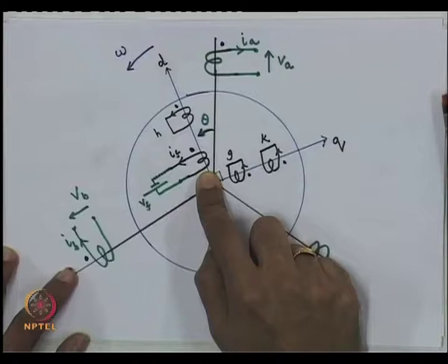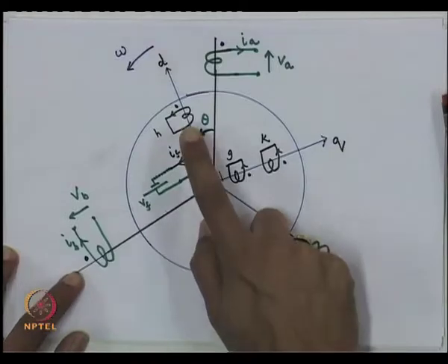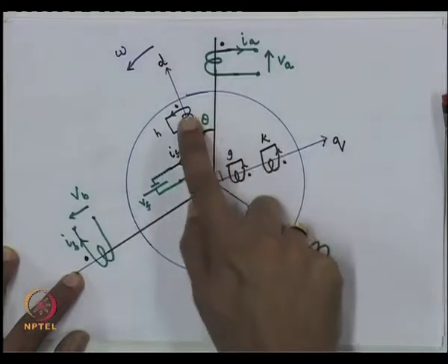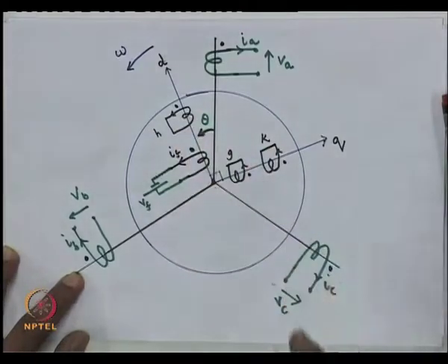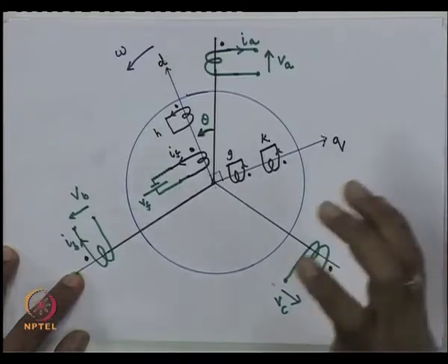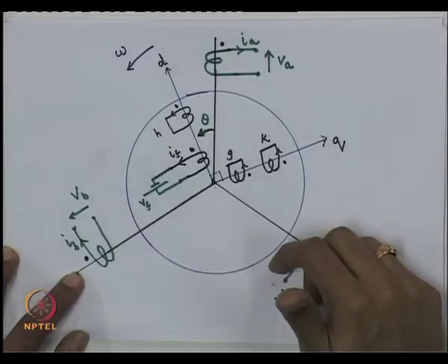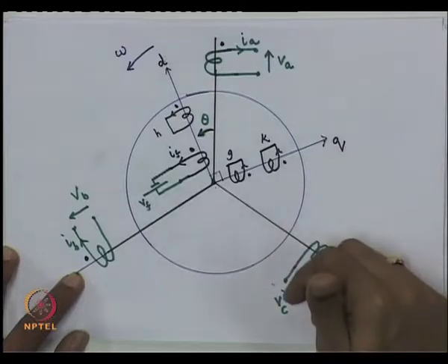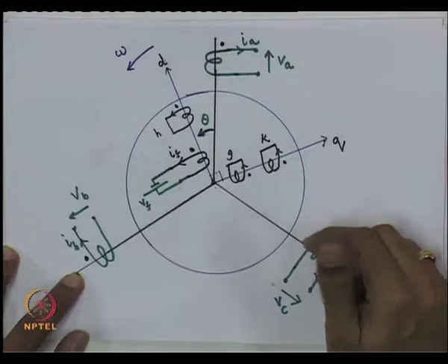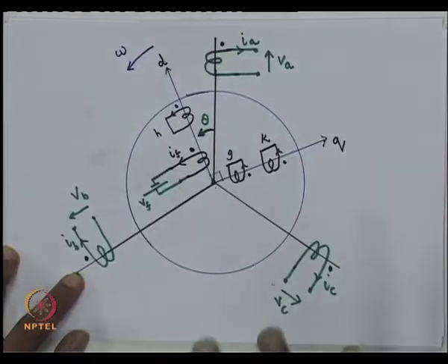Now, one more interesting point which you should note is that you also have other electromagnetic circuits, though they are not necessarily in the form of windings. For example, in a synchronous machine, a steam turbine driven generator may have eddy currents on the rotor. In case of hydraulic driven turbines, you actually have a squirrel cage like winding on the pole face.